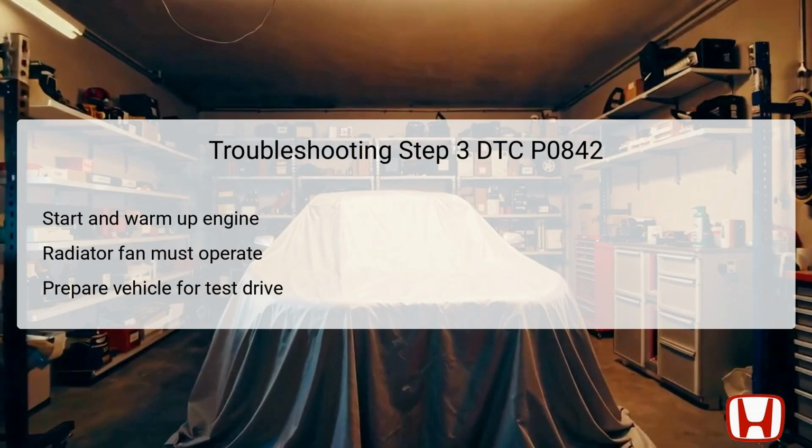After the engine has warmed up sufficiently, it prepares the vehicle for a test drive in order to monitor the system's behavior under normal operating conditions. This step ensures that all components, including fluids and electrical systems, are functioning effectively. By introducing real-world driving conditions, it allows the technician to evaluate whether the previously logged DTC persists.